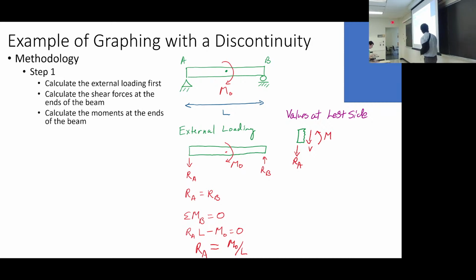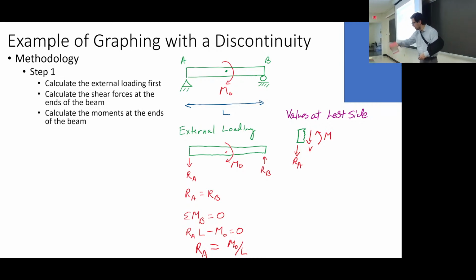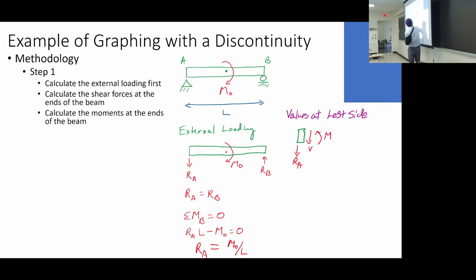But here you can kind of see, when I choose these external loads, the bending moment is going to be like this: if I put this box here and start twisting it, on one side I'm going to be pushing down, and on the other side I've got to hold it down, if I have statics. So you can see that this left side is holding it down, whereas the right side is pushing up against that moment that's being applied.